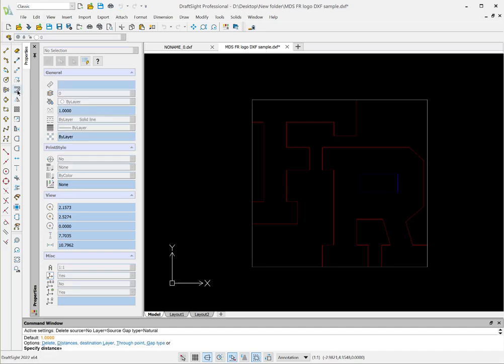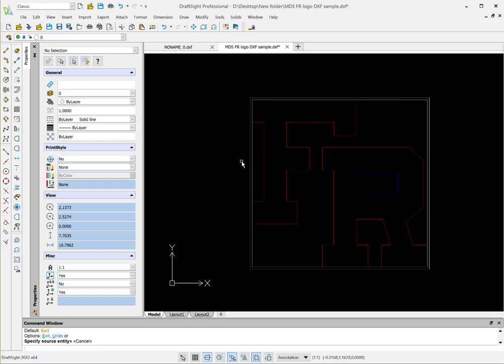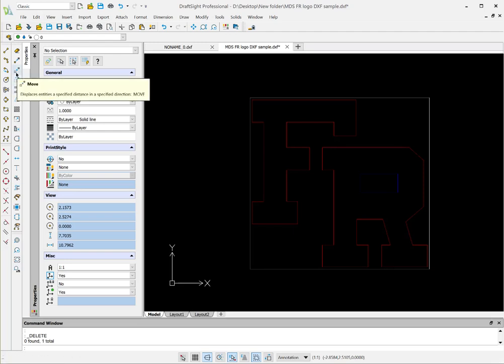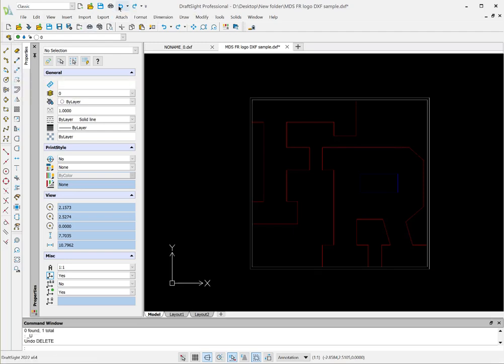So I'm going to offset 0.06 for 4-ply mat board. This out. Okay, so that would be like the face paper, and this is the bottom of the bevel. So let's delete that. So that is my clip art. Now I need to move this back up to the origin. So let's move, because remember, let's just undelete that. Remember, this is where my origin originally was.